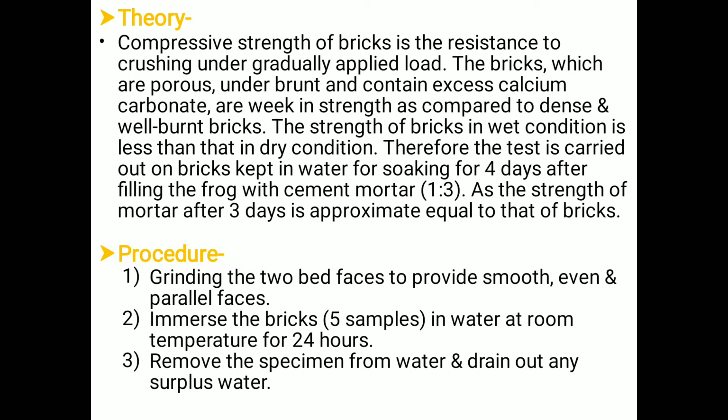After filling a frog with the cement mortar, 1:3 ratio we have to use, as the strength of the mortar after 3 days is approximately equal to that of the brick. Now we will discuss the procedure which has to be followed for conducting the test. First of all, we have to select any 5 bricks from a pile.